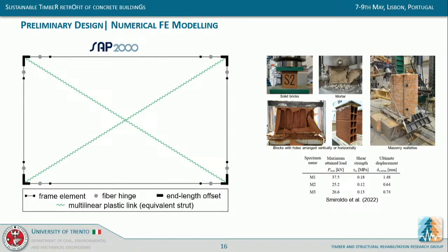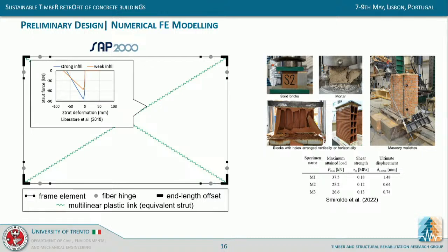We had some very refined modeling we did in Abaqus and so forth, but we went for simplified models that you see here, where the frame is modeled with frame elements, concentrated plasticity. The infills are modeled as equivalent struts by adopting the model proposed by Liberatore and others, with material properties that were calibrated on previous small tests, material characterization that we did in our laboratory.